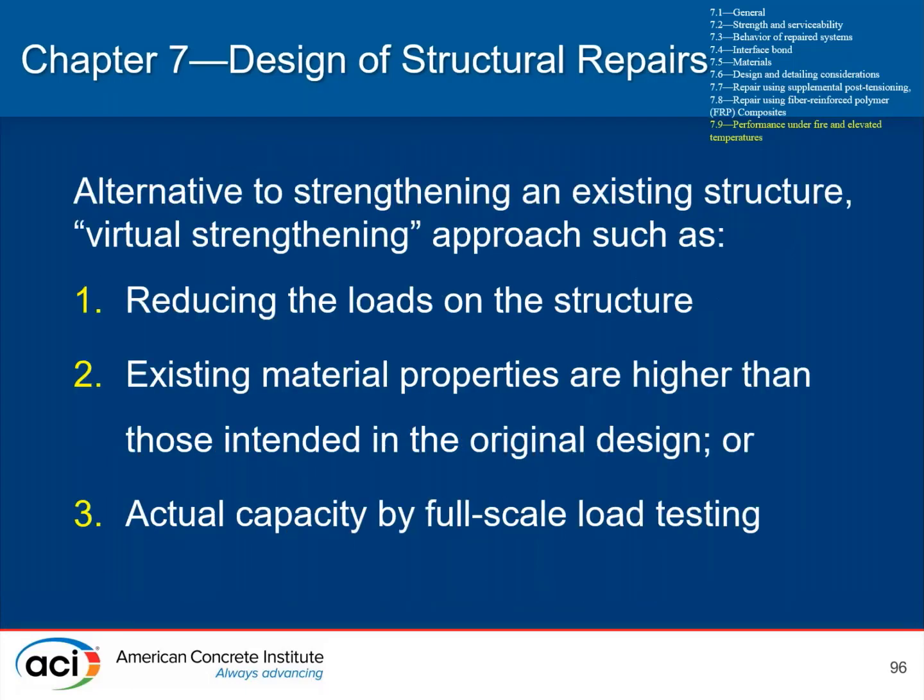There's also the concept of virtual strengthening that's discussed here. An alternative to strengthening of an existing structure, if there's some sort of a deficiency, is to virtually strengthen it, either by reducing the loads on the structure or confirming that the existing material properties are higher than those intended for the original design.